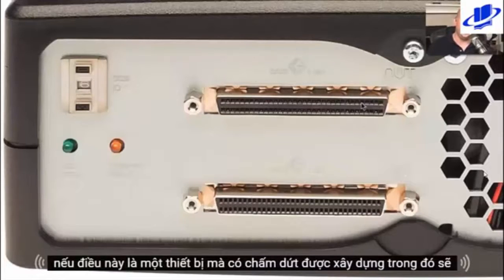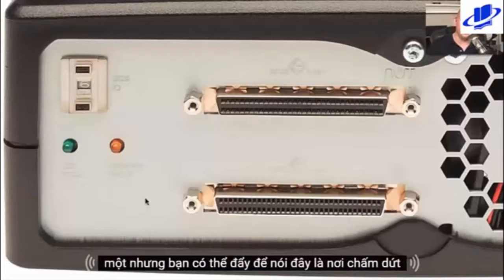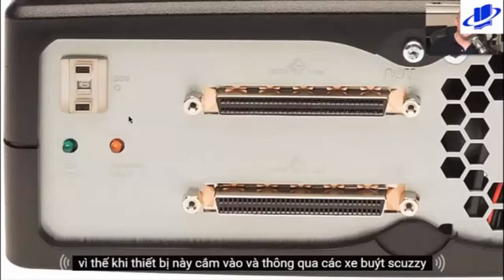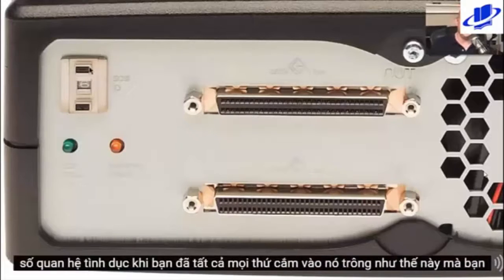If this was a device that had the termination built in, there would probably be a connector on this device, or a button you could push to say this was the terminating place. And you can also see the SCSI ID number built right into this as well. There's little buttons that would allow you to change that SCSI ID. So when this device plugged in and communicated across the SCSI bus, everyone knew that this device was SCSI ID number 6.